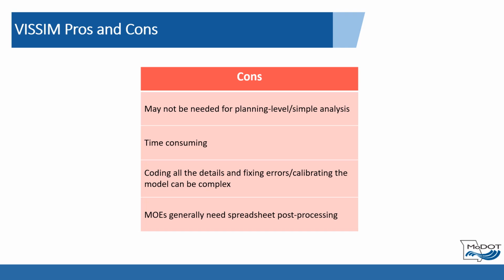For example, without scaled conceptual designs to code network links on, Vissim would be cumbersome to develop an analysis for a project where many unknowns may still exist. Deterministic software packages would be more efficient in this case. Likewise, if new signals are being evaluated, the use of Synchro or a similar software tool that can quickly input basic parameters and evaluate different timing options would be a better choice than Vissim.